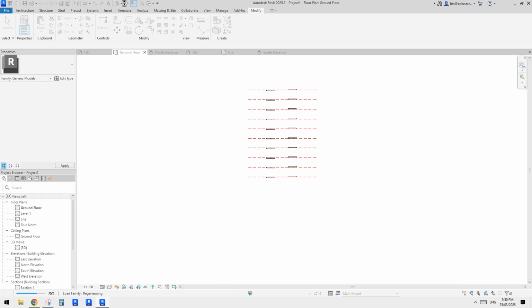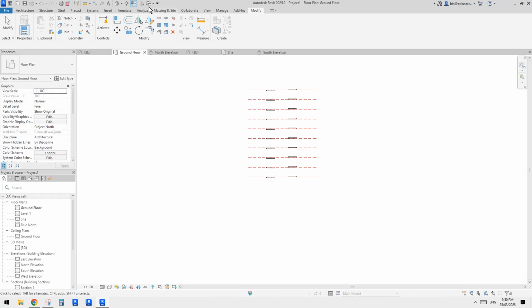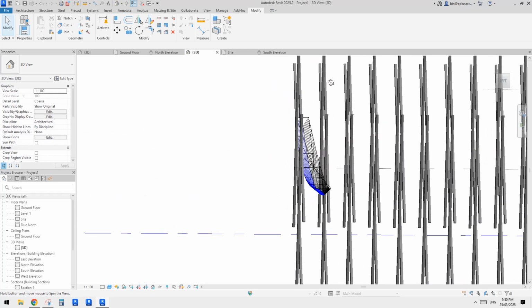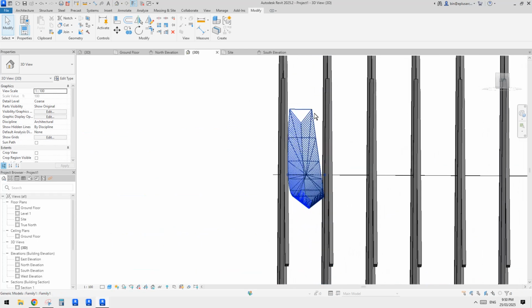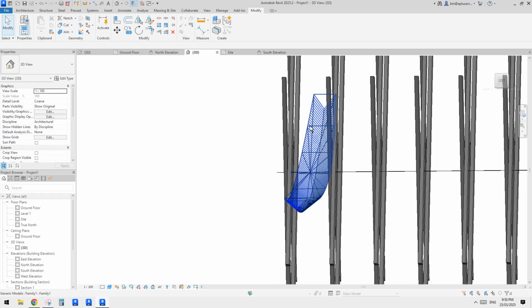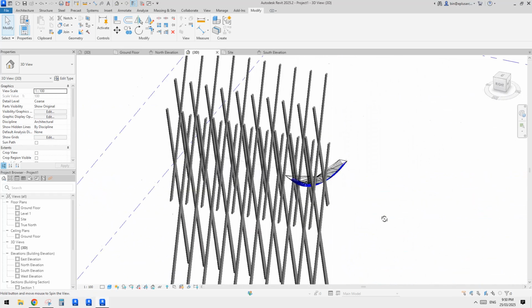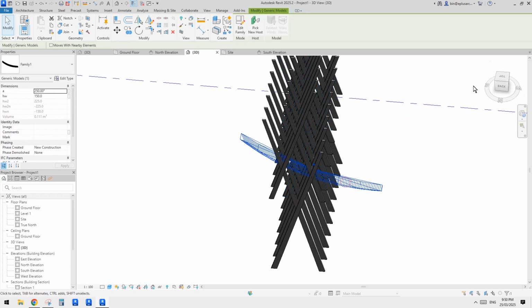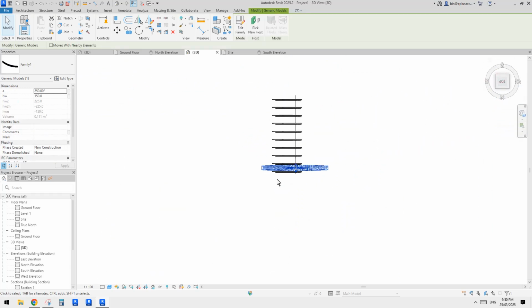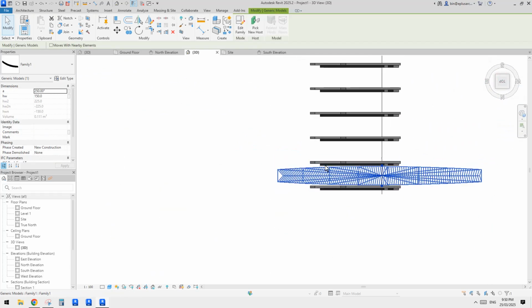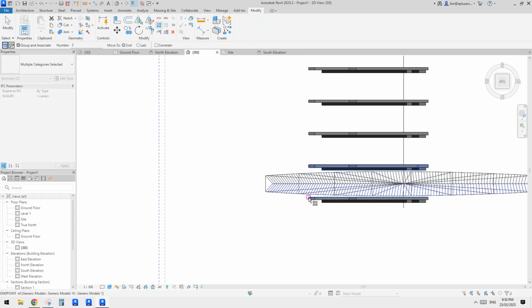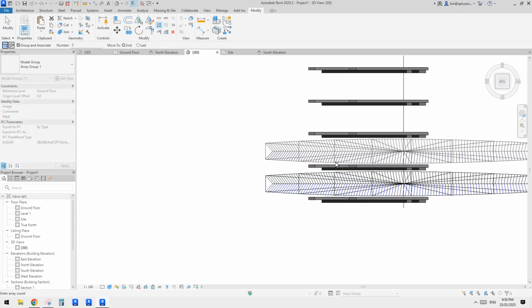go to 3D view. Yeah, so it's a little bit slow. Okay, so go to 3D view. So now we have some structure members. So you can see all these model lines. Okay, and so once you're quite happy with this one, I think we can probably just do an array. So let's try AR here to here, maybe type 10, and finish this array.